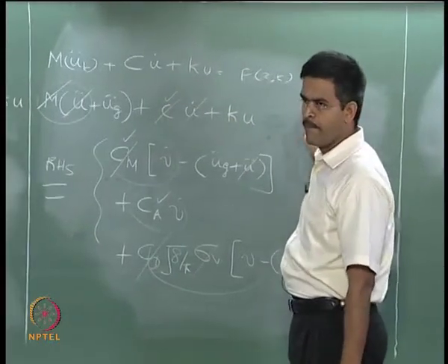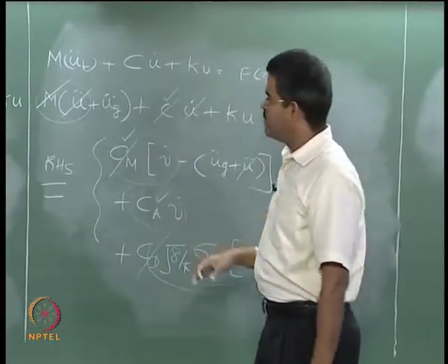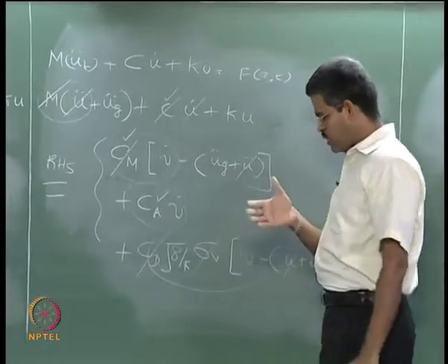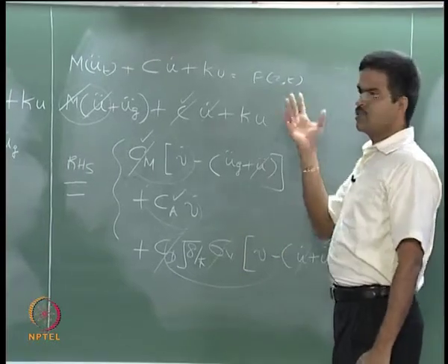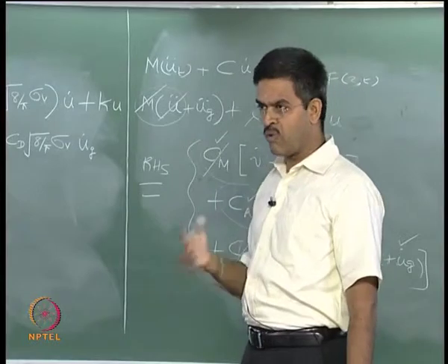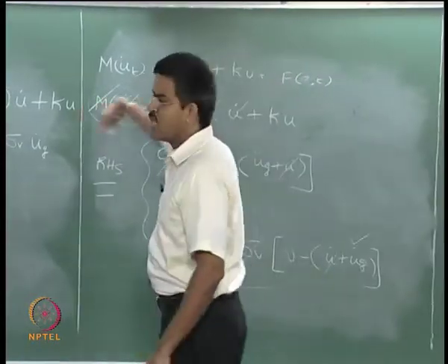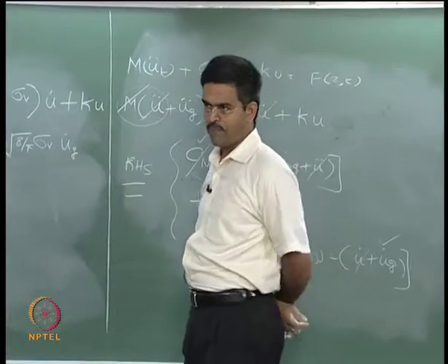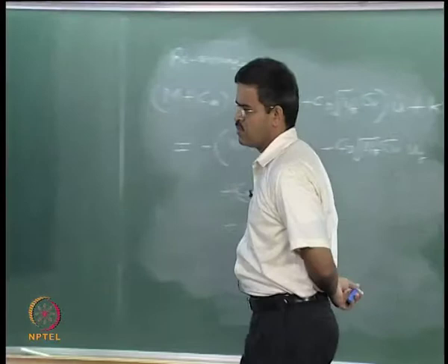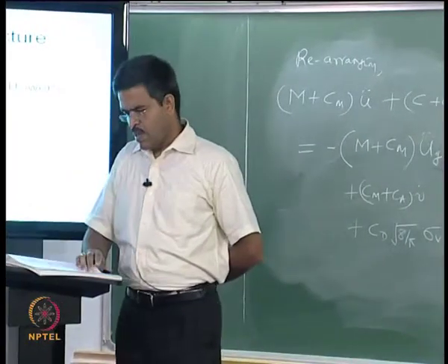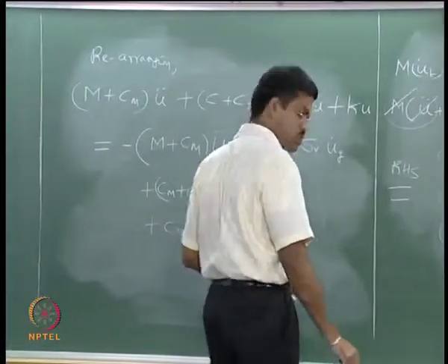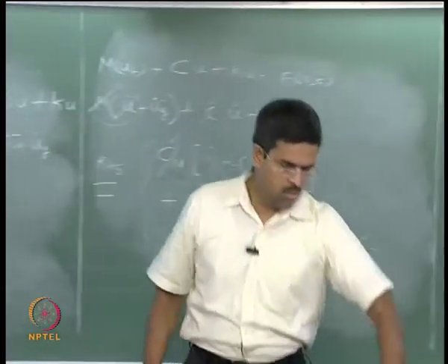It is a classical form which we derived, or assembled and rearranged, from the original equation of motion. This is class A, where my structure or the platform is resting on the seabed, and the seabed is moving horizontally. The ocean does not move horizontally; cylinders will vibrate and cause movement, but that is neglected. Therefore, the radiation damping term is not there in the system, only viscous damping is there. So, classical form of equation of motion for this. Now, what do we know from this equation and what will we solve?